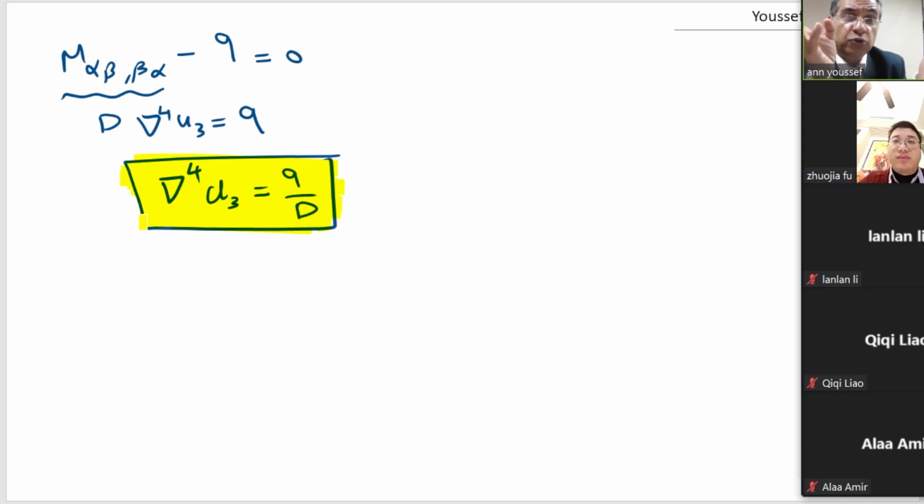And then we will be able to compute the integrals, whether they are regular integrals or singular integrals. It's very important to talk about the C matrix or the jump term, because when we go to formulate the hypersingular equation or the traction equation in order to model the two crack sides with displacement equation and the hypersingular equation, we'll do the same, but at an advanced level.